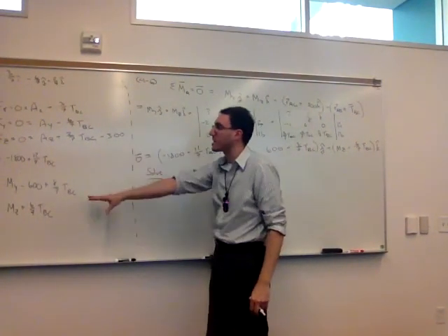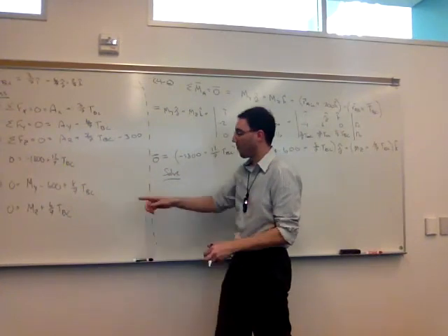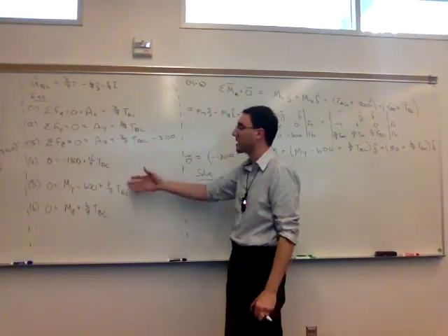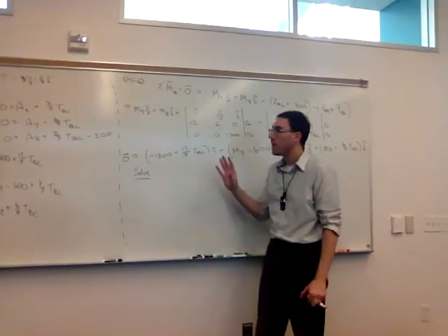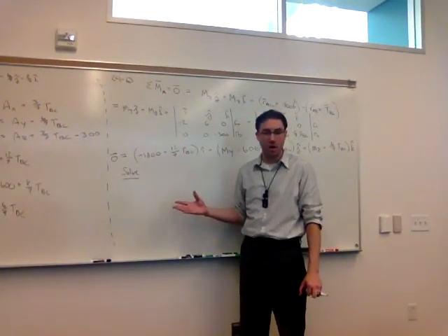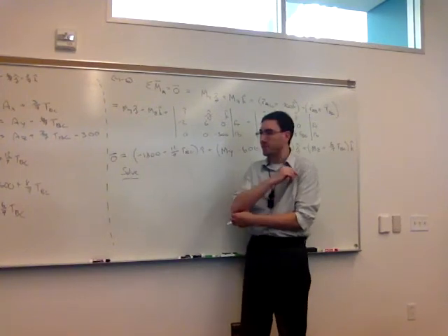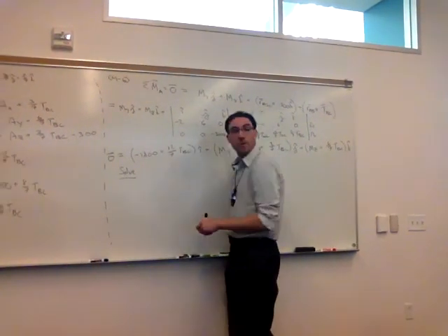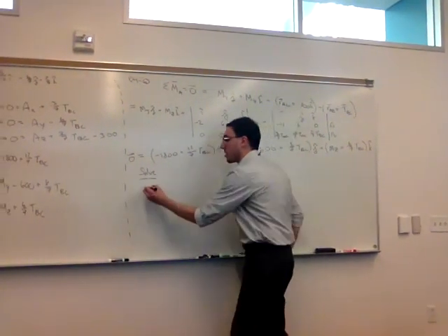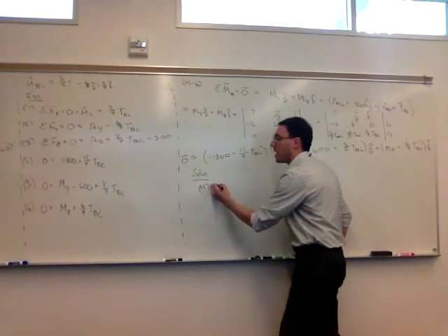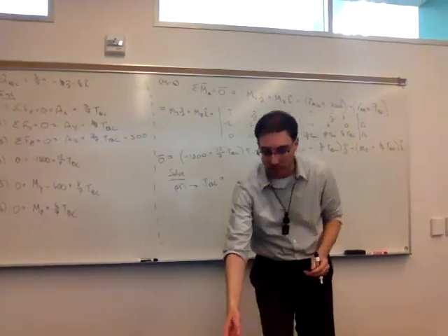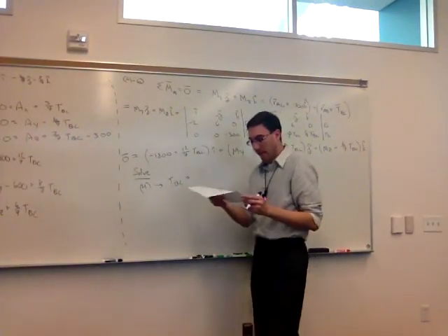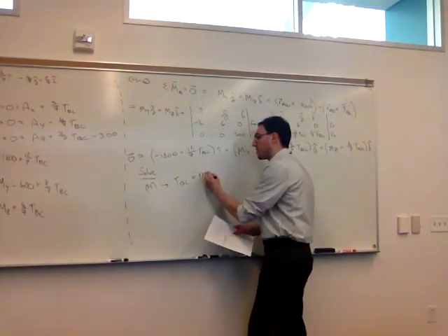So we now have our 6 equilibrium equations. If we count up our number of unknowns, we have 6 unknowns. We have 6 equations, so at least we know it's a solvable system. This one by hand is not bad to solve. There will be ones that are very tough to solve by hand. So if we go to the solve step, right away we can start with equation 4, and right out of there we can get the TBC, the tension in rope TBC, is 1,050 pounds.